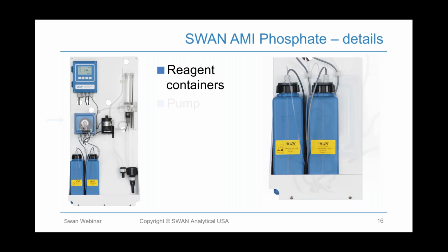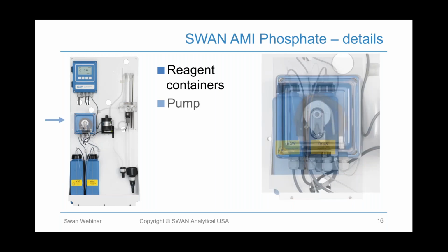I wanted to highlight our reagent and sample delivery system. This is essentially a peristaltic pump that we turned inside out. The rollers are on the outside, and you can see that we have these preloaded clips, so there's no more rebuilding of reagent pumps, and you don't have to find a way to supply air to the instrument or have an air pump that has to be replaced or maintained to drive reagent delivery.